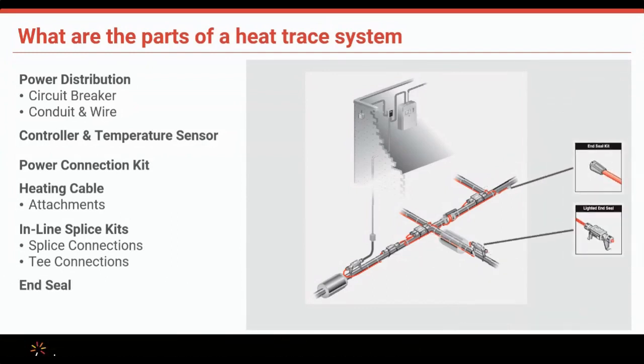And then finally, wherever you're ending your pipe, you want to have a termination kit that is approved with the product. I have gone out to the field and found, when I get to the end of the cable, that it is electric tape tying this section down. That's not an appropriate or approved way of doing it. So we always need to have end seals.